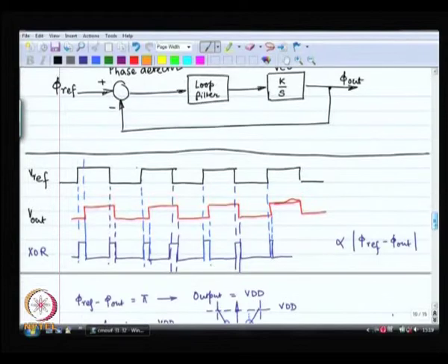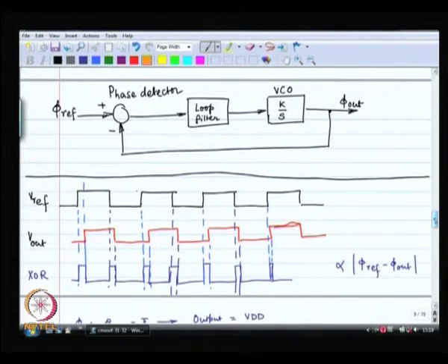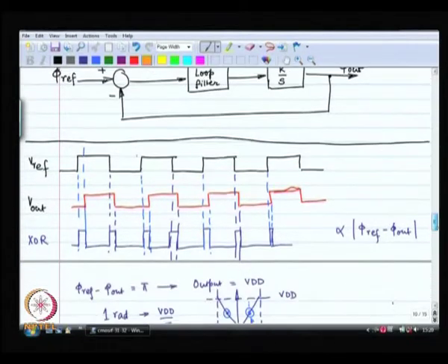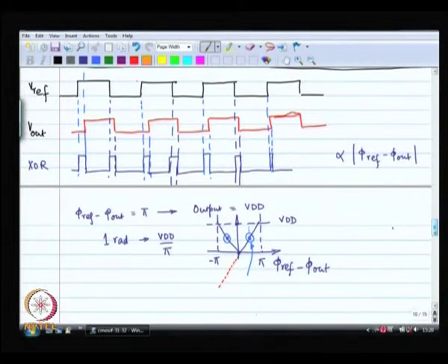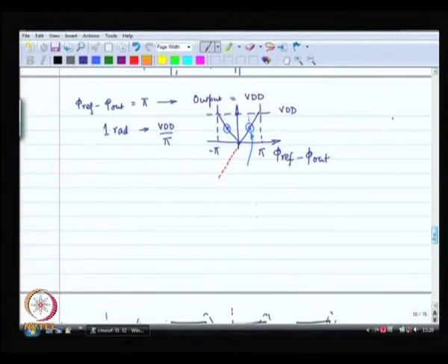Next, what we did in the previous lecture was we tried to build the first building block, the phase detector. Now, this phase detector, we figured out that the input signals are really digital signals. So, there is no reason why the phase detector should not be a digital circuit. Our first experiment was with an XOR gate. We found out that the XOR gate kind of works, but it works at a bias point of pi by 2 or minus pi by 2, as the case may be.